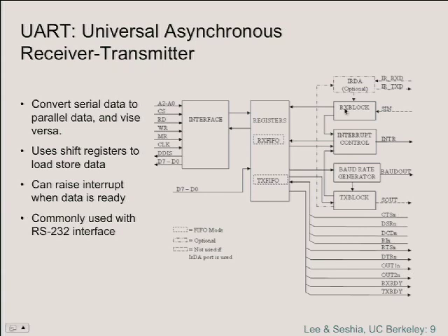There are all these other interfaces that are used. For example, you can ask it, again by reading a memory mapped register, whether there's a byte there. Is there a byte for me? You can also ask it to wake me up when there is a byte for me, by asserting an interrupt. These other lines are used for that, okay? So let's talk a little bit about how that works.